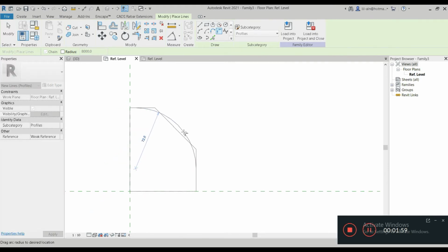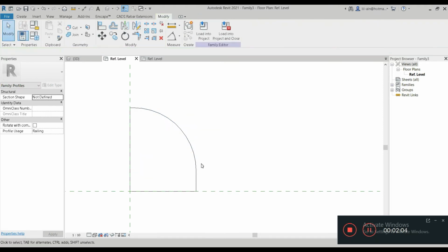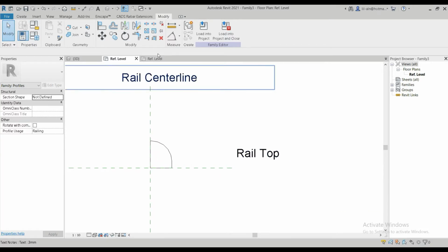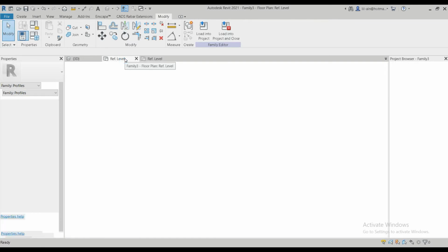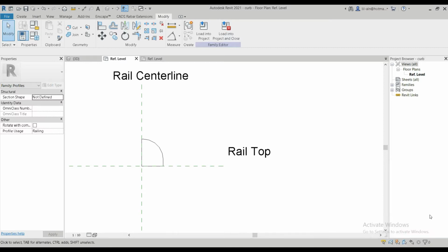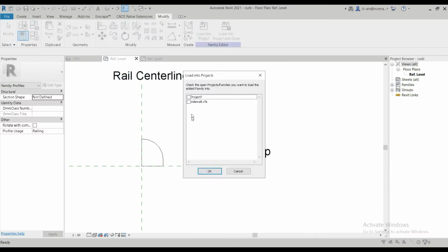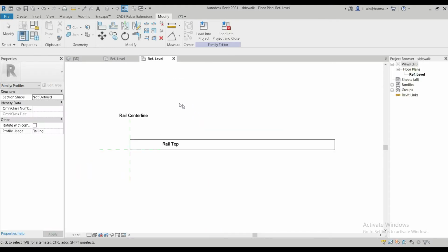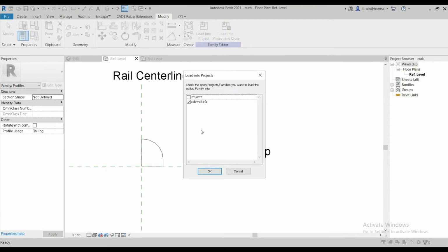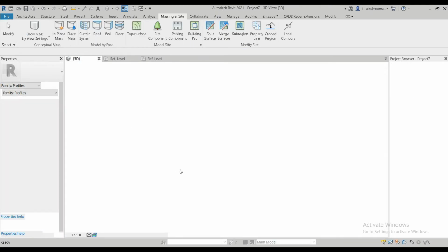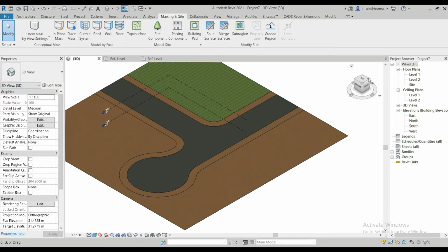In other videos I'm going to cover different methods. There are a few different ways of doing this. People are even using floors to do this, and you can even do this by building paths, all right? So there are a few different ways of doing the same thing in Revit. It depends on the workflow of the user. In this case, I'm using the rail method. I believe this is the most effective method when it comes to roads and curbs, because the shape that you make changes with the topography, okay? In this case, our topography is constant. It has a zero elevation throughout. But in the rail method, the shape of the object changes with the topography. So that's the best thing about this method.